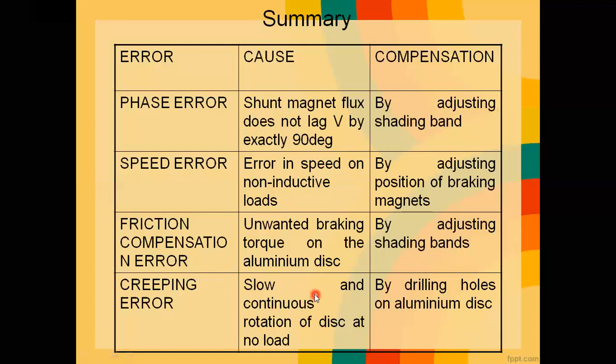So here I have to include one more thing, that the cause of creeping error is overcompensation of friction, which results in slow and continuous rotation of the disk even at no load.